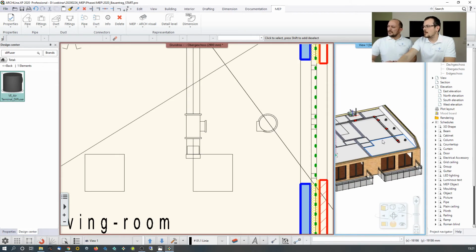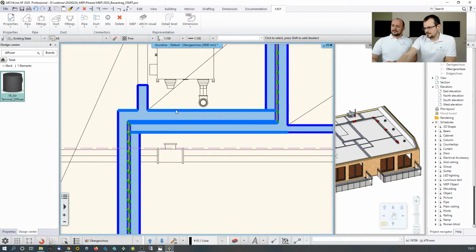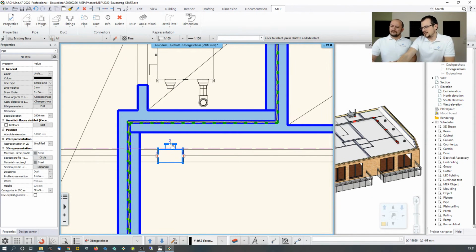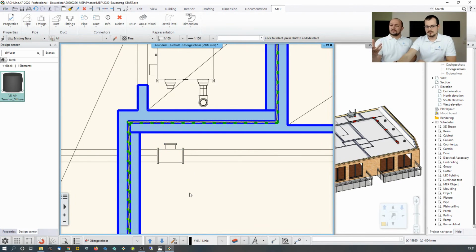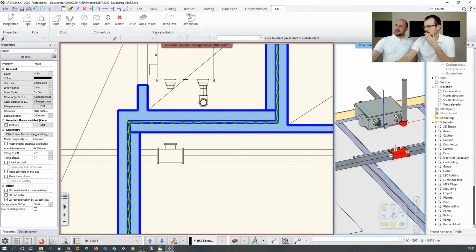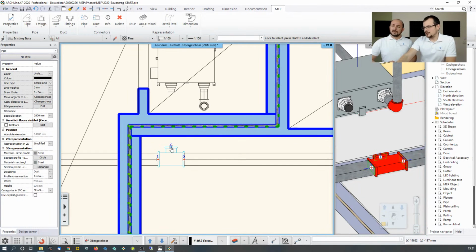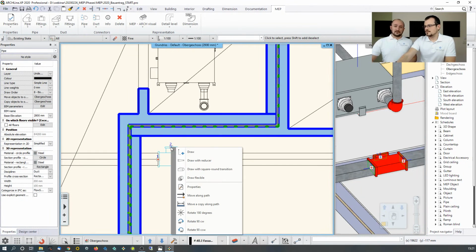That's right. Now, what comes next? I have to connect the T with this unit, and I do it from the T itself. And actually, there is another issue here, which we will solve: the cross sections are different. Here we have a rectangular tube duct, but there the exhauster, the heat exchanger, has a circular intake. So we have to not only convert the shape, but the diameter is different as well. So all kinds of mess you can imagine, but it is all solved. So you will see how to solve this sort of system.